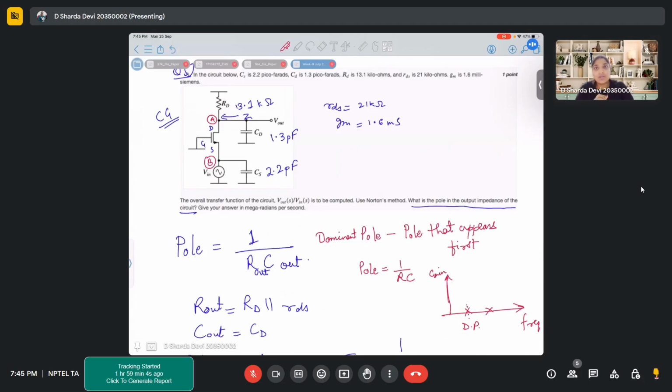If you change the dielectric material, you will change your capacitance. If you change the area, you will change your capacitance, and the distance between the two plates will also affect it. You can think of it as dq by dv, which is also capacitance. From the basic formula of parallel plate capacitance, it is epsilon A by d. You can go either way and explain how you are looking into the problem and what the basic factors are which are changing.